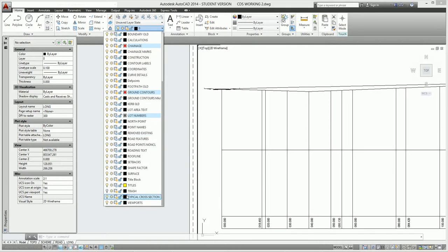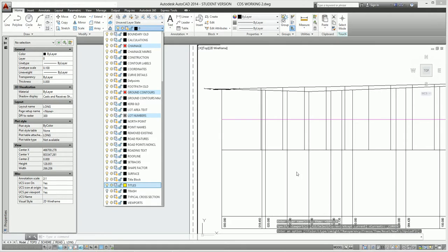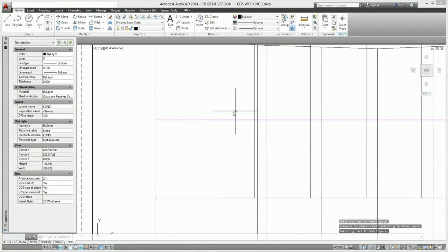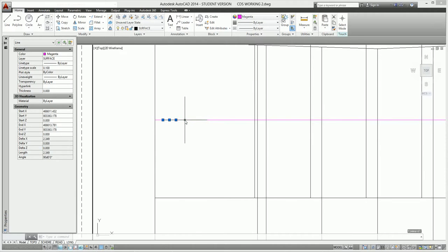So I'll turn the surface back on again just to show you a little bit more about how that works. Now what I've done here, with my spreadsheet on my second screen, is put in all of the little distances that we measured, and made sure that they key into the various points from the alignment, so that they all fit within a millimetre or so.